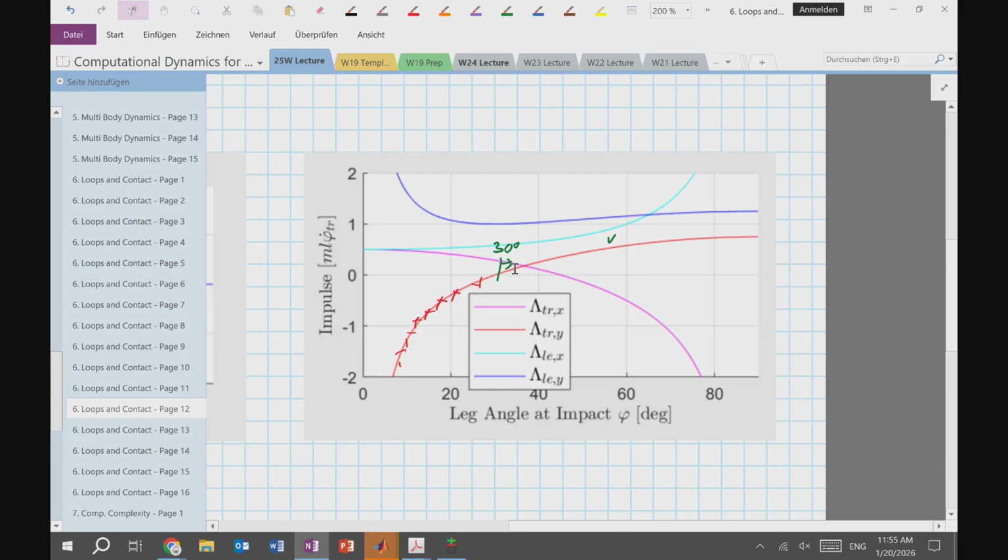So in this range, we still have valid solutions for very large coefficient of friction, but for reasonable coefficient of friction, at some point we will start to have sliding. And indeed, we have to go ahead and assume that we can have sliding with infinite friction. That sounds totally counterintuitive at first, to say I have sliding with infinite friction. But a coefficient of friction is not saying you get infinite forces. It just says something about the ratio, or more precisely about the tangent of an angle.